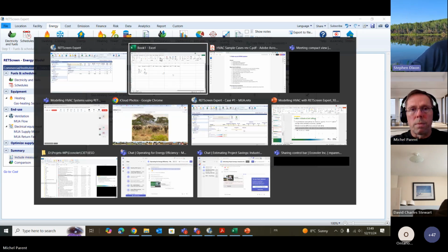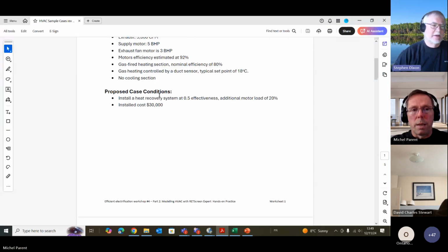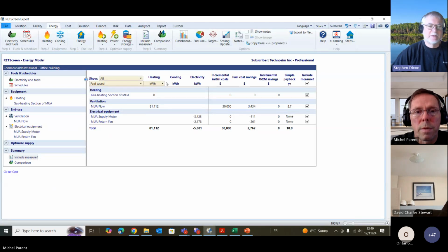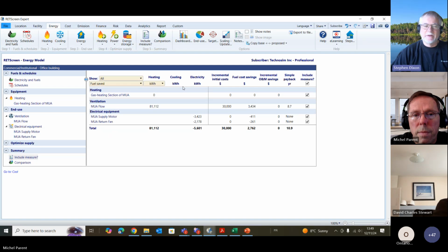Before you jump to that one, Michelle, I just want to explain the nuance here. Just go back to your summary screen there. Some people might have noticed that the simple payback has gone from 9 years down to 8.7 years for the makeup air unit, the ventilation piece here. Does anybody think about why that could have occurred? It's like there's more energy available in the makeup air to heat the makeup air. Where is that energy coming from?